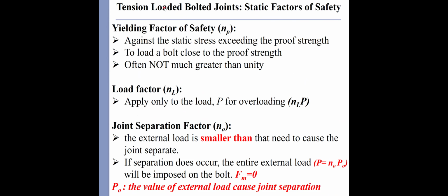Okay, that means look into the other topic, which is related to safety factor. We have to design a bolt, so of course we need a safety factor. Here, we're only going to discuss the static loading case. So we have to think of the yielding factor of safety, the load factor, and the joint separation factor.